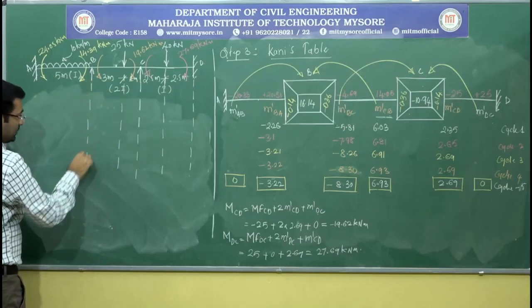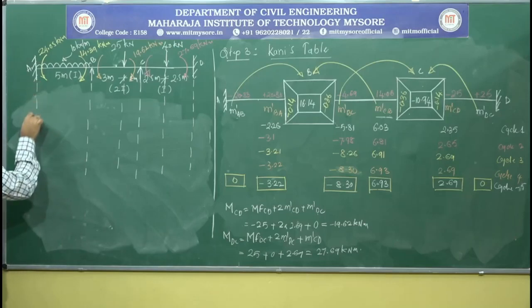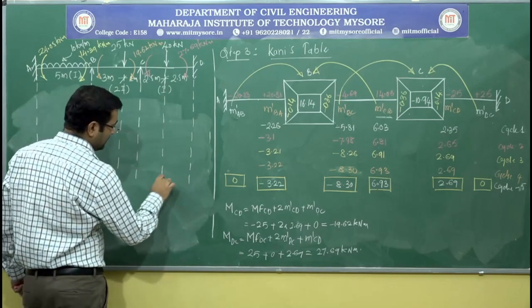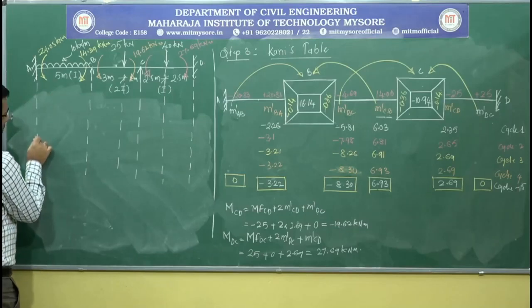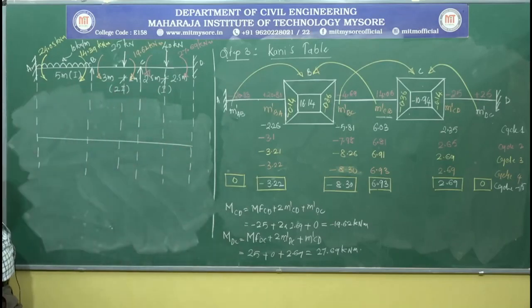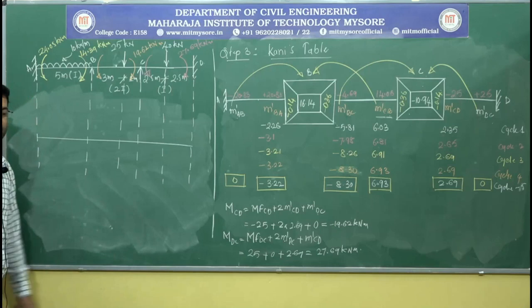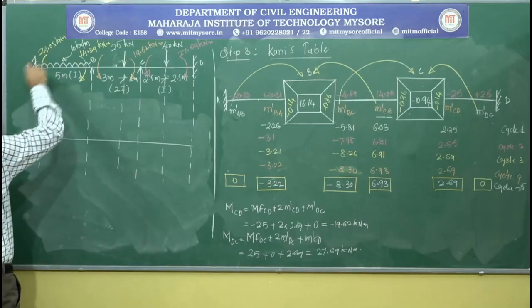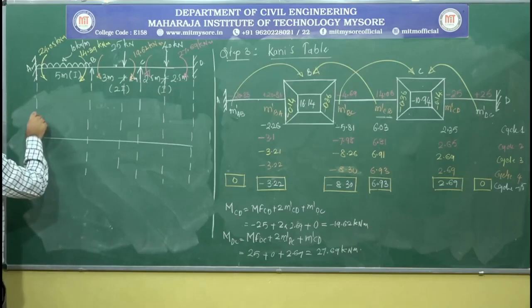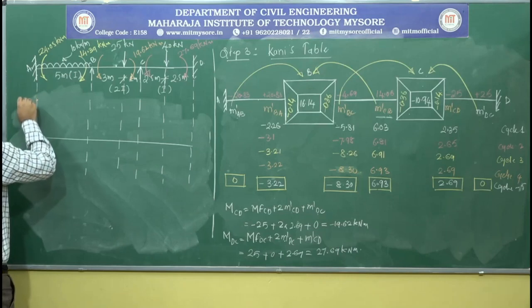Okay. So what I will do here, I will draw the bending moment diagram by superimposing the end moments with end moments calculated with the maximum bending moments. Okay, right. Now you can see the bending moment at A is 24.09. So I will mention that somewhere here,